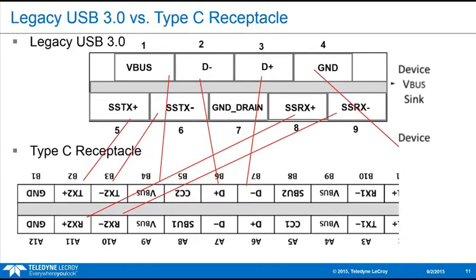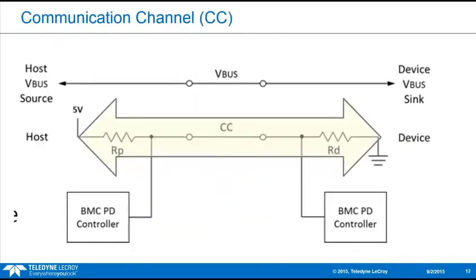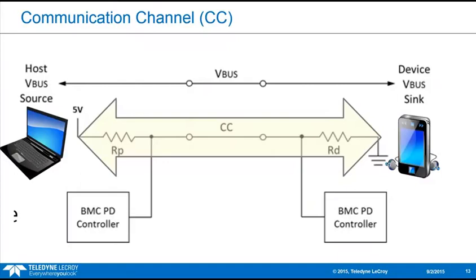So we need to look at that, but before we do, the other key feature is that the entire cable is reversible. Either side can be attached to the host because the plugs are identical, right? But we still need to maintain the logical host-to-device relationship. So when you're connecting a Type-C cable to a receptacle, which row of the pins am I going to use? Okay, that's the first order of business with Type-C. And then identifying the host-to-device relationship is the next critical step.